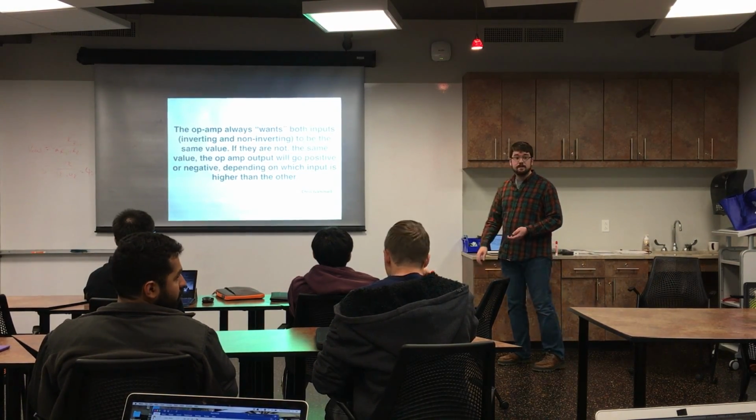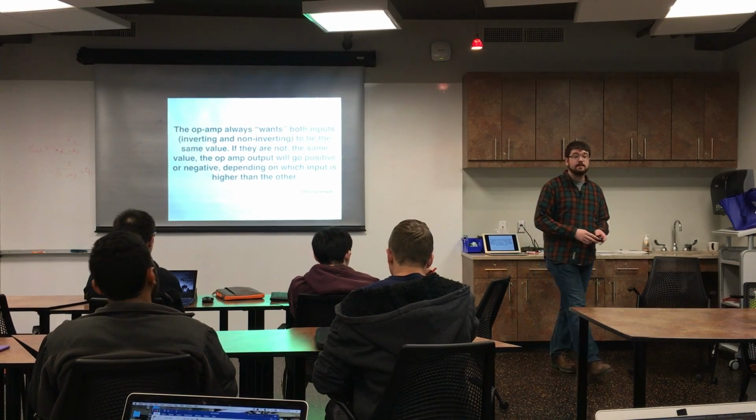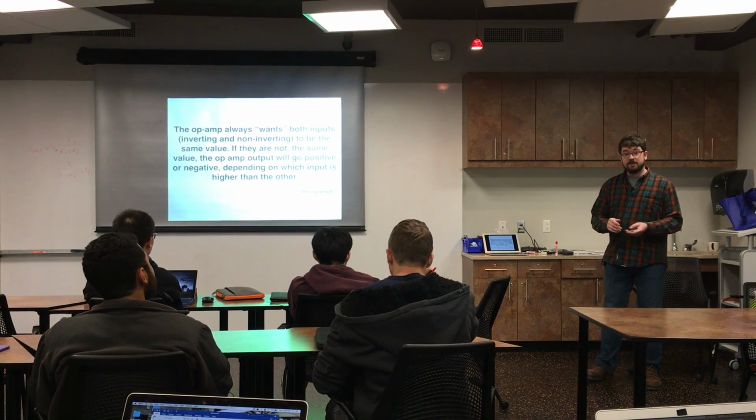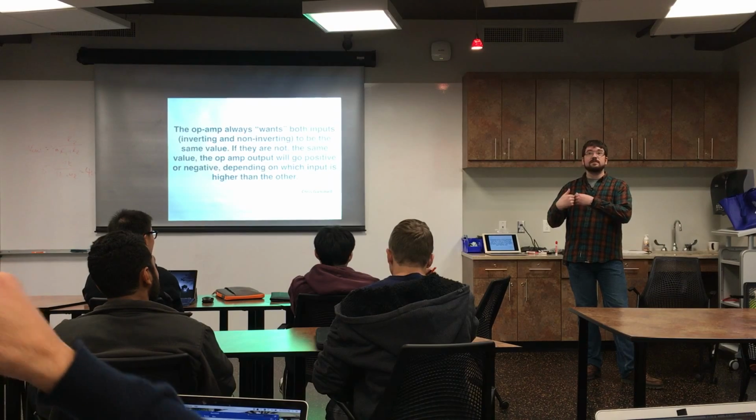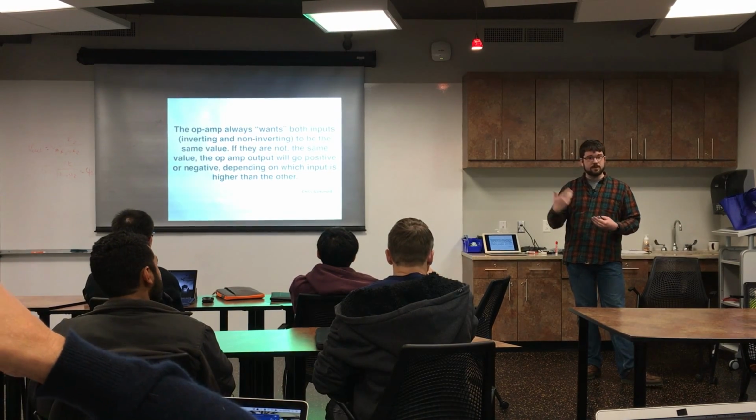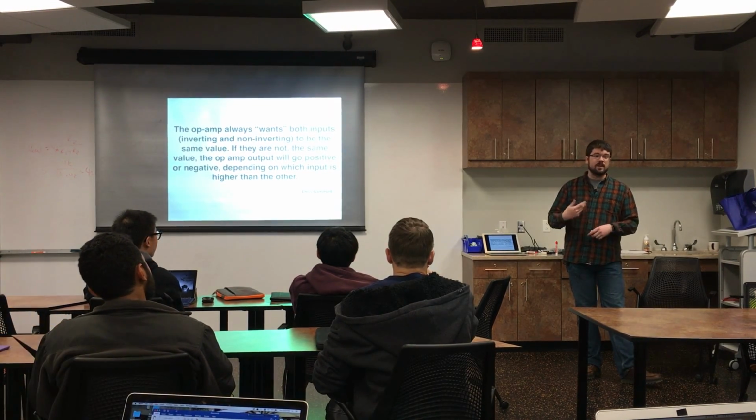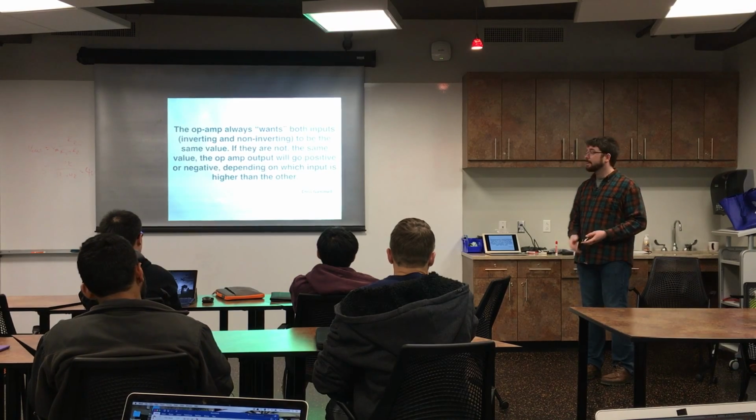Does that mean which has a higher absolute value? Yeah, so if the non-inverting input is higher, then it will swing positive. If the inverting input is higher, then it will swing negative, right?